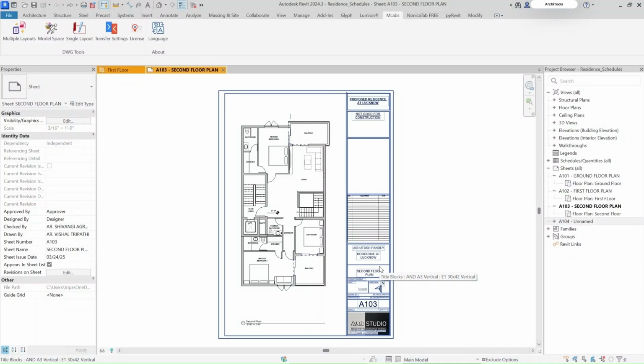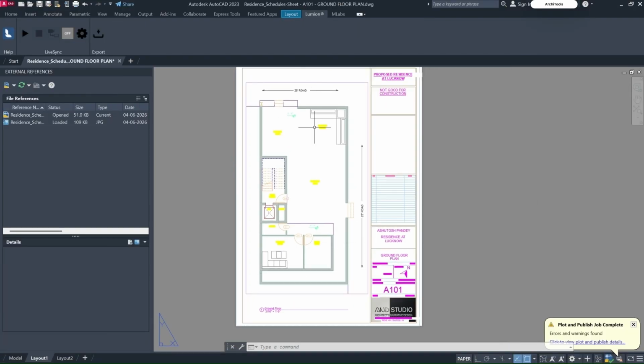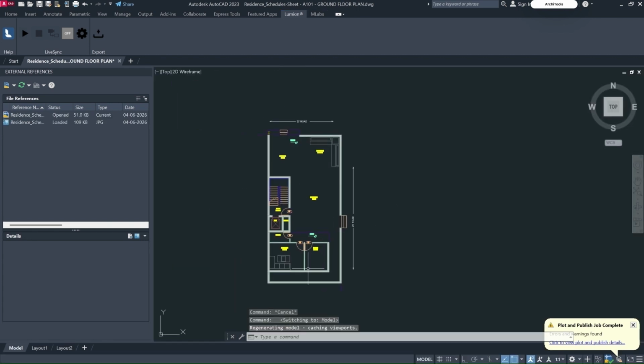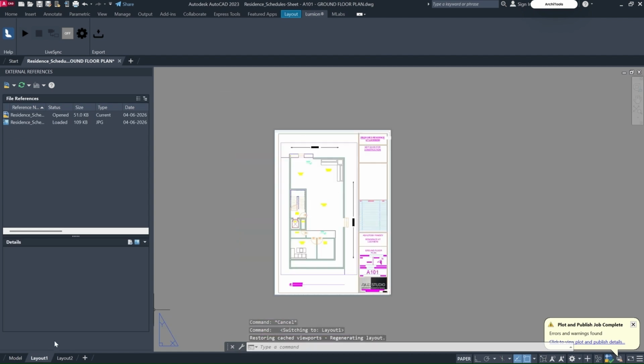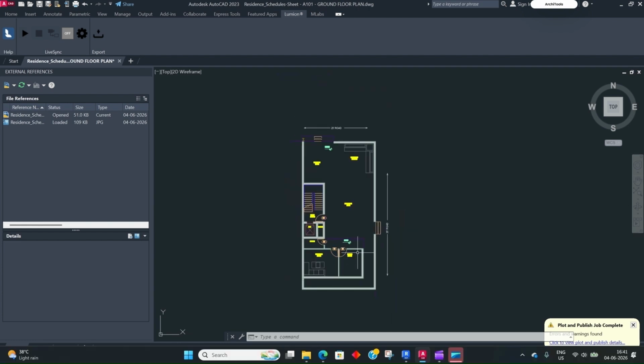In this video, we will discuss the various possibilities in which you can export your sheet into a CAD file from Revit. The one generic method in Revit is that when you export any CAD, you get, first of all, a layout in which your sheet is presented, and inside this layout you have your view, similar to Revit itself. So the view is inside your model and the sheet part is provided in your layout. If you export all the sheets, they will be exported in individual CAD files. This is the only method available in Revit.